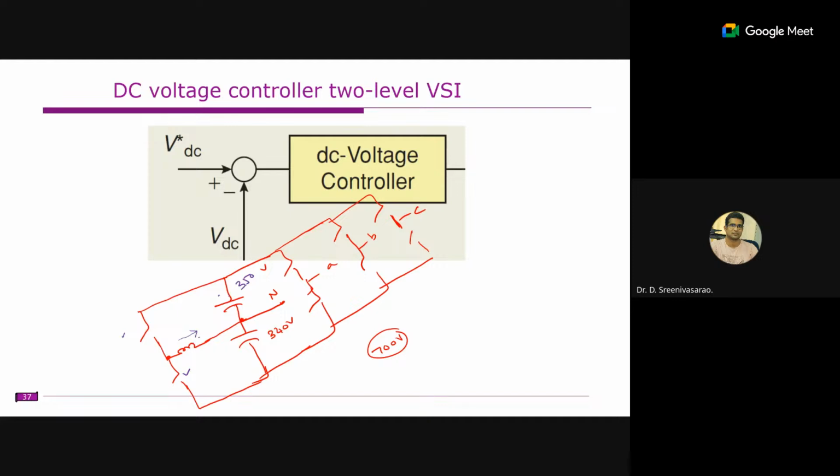Here the inductor current will not change its direction, right? So therefore it will charge this capacitor. Once again it touches 350, and the capacitor voltage is recovered. Again, if it touches 350 volts, this is the point where this switch will be off. So if the upper capacitor is excess charged, this charge is transferred to the inductor, and again from the inductor to the bottom capacitor.